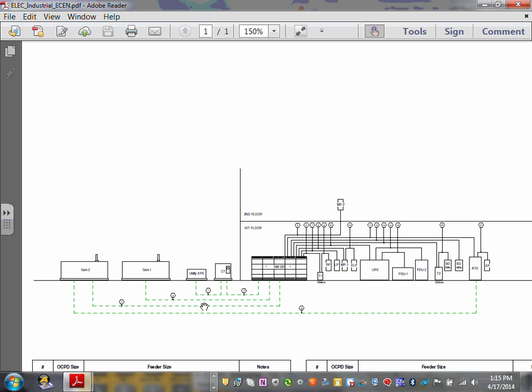Efficient power system. But the problem with the 480/277 is you have to step it down to 208/120 and feed receptacles. So there are losses in the transformer. I've heard this over the years; you can agree with this or not. This building is definitely a 480/277.